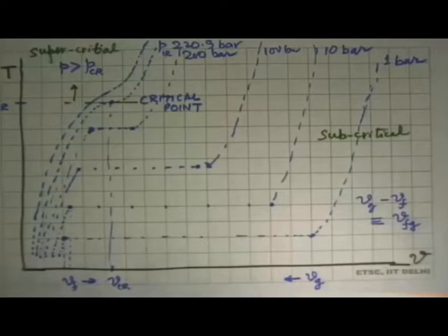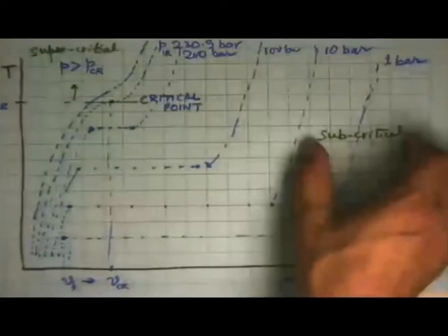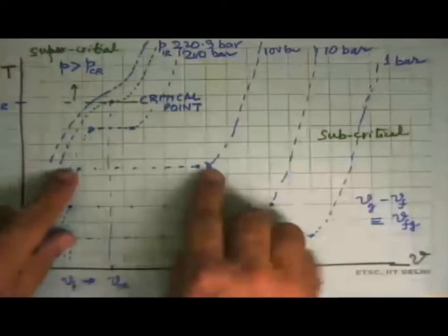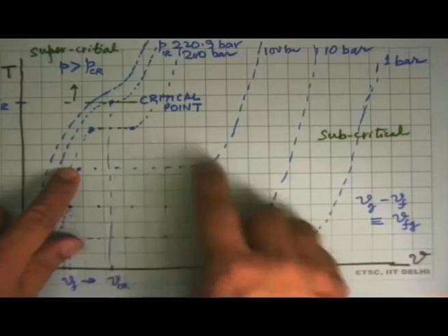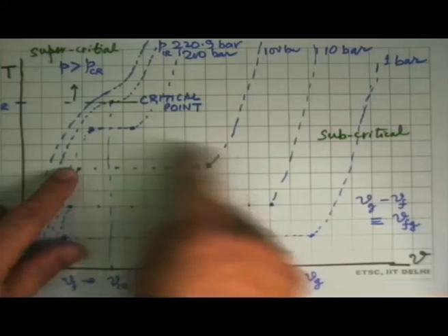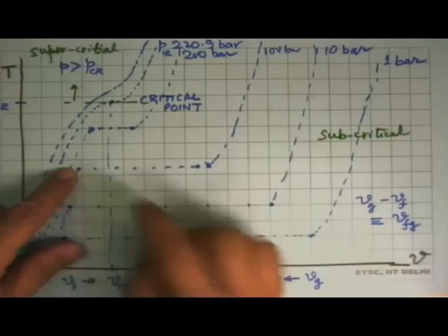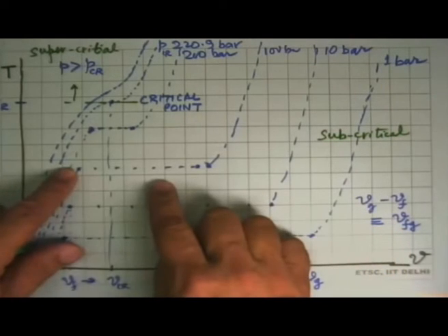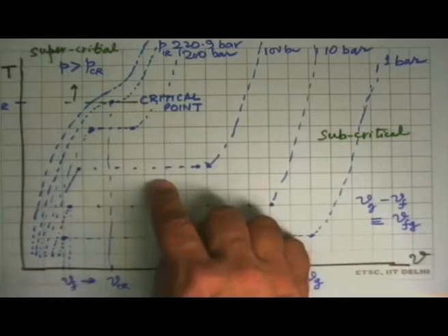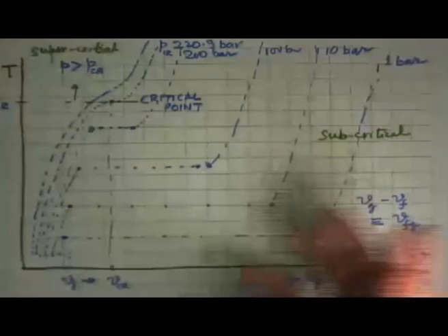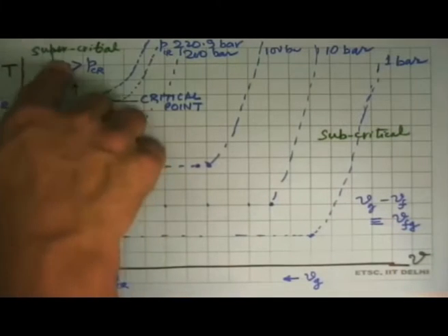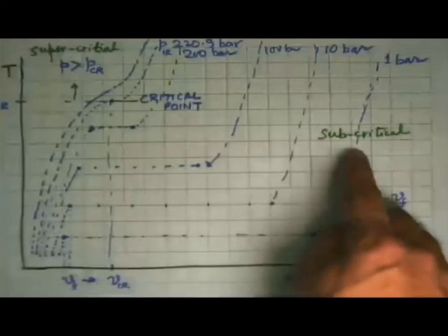And the difference was that in a subcritical power plant, you got to design some part where the phase change takes place. In a supercritical plant, this issue is not there. And thermodynamics tells you a very simple thing, this has a very big implication on heat transfer and the mechanical design of the boiler itself. There are completely different philosophies for this type of a boiler versus this type of a boiler.